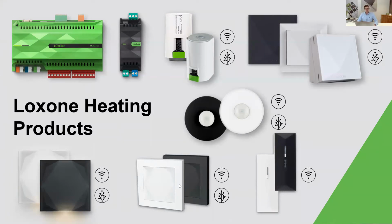We've then got the touch switches, the touch and the touch pure. Again, air or tree, both of them contain temperature and humidity sensors. And then finally, door window contact. We only make an air version of a door window contact. If you want a nice flushed in version that's slimline, go for a standard alarm contact, wire it into a digital input. But the one that we do is the air version.